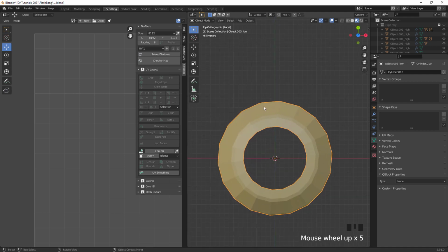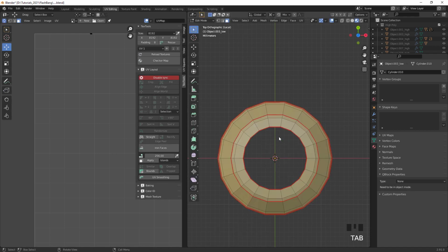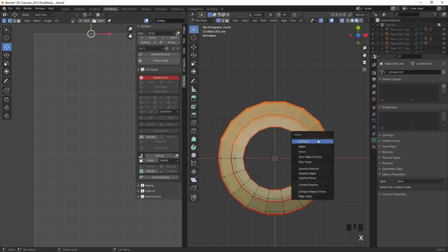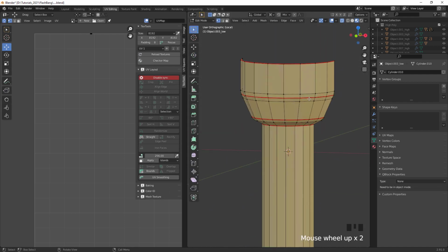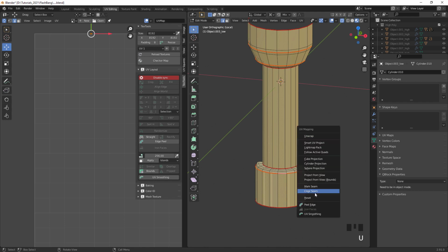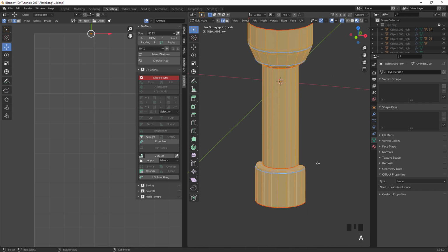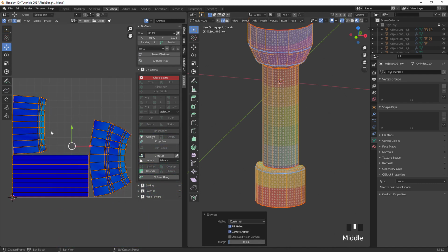Now let's work on that piece. And I actually want to rotate that with our Ctrl snap in a 5-degree way so that this is perfectly straight. I don't know why it was distorted before. I'm going to delete these vertex points so that we can then unwrap only half of it so that we don't consume so much texture space. Let's select these edges and then clear those seams. And everything else we can already just take like that here.